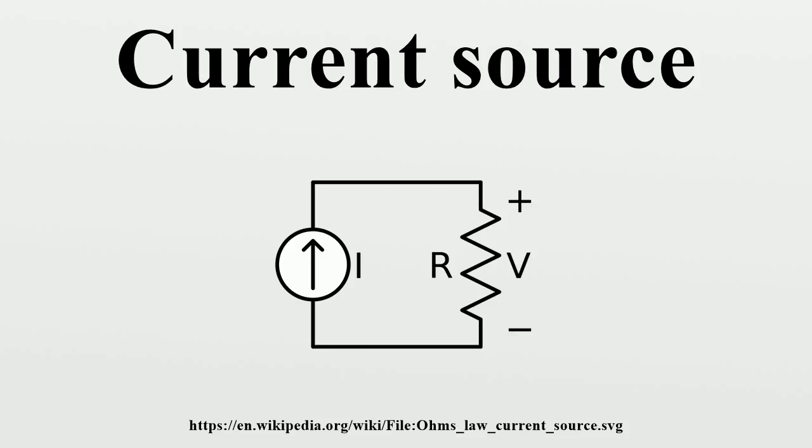LED current source. The Zener diode can be replaced by any other diode, e.g., a light-emitting diode LED1 as shown in Figure 5. The LED voltage drop is now used to derive the constant voltage and also has the additional advantage of tracking VBE changes due to temperature. R2 is calculated as in R1, where ID is the LED current.